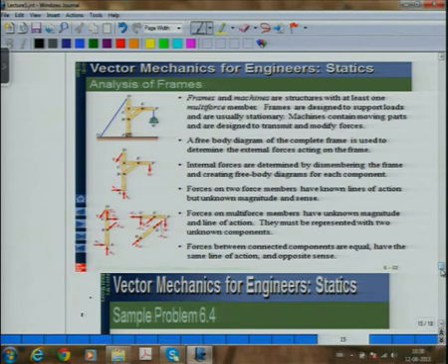In this frame, what I realize is BE is a 2-force member, if I assume that all weights are negligible. So the force along BE, as we have already discussed, will be along the line of BE.